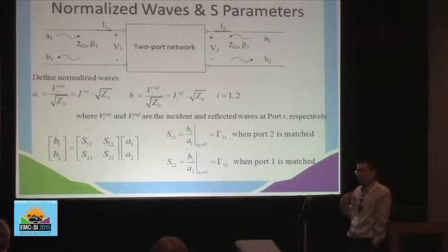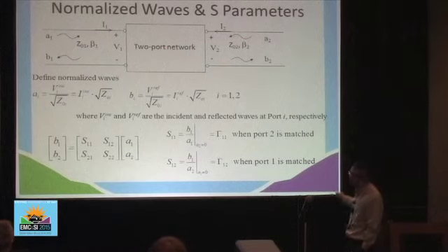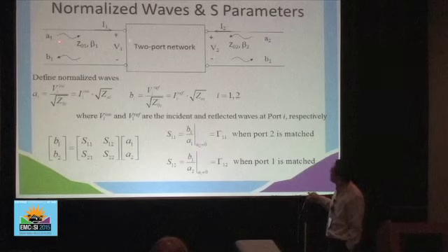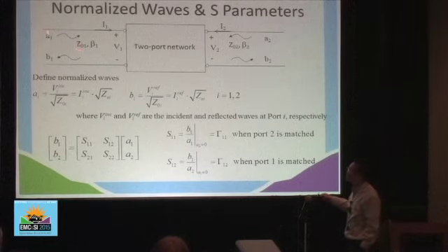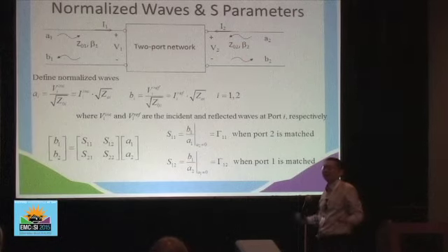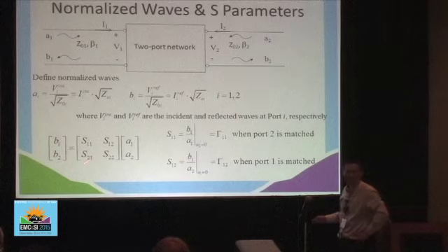So at the higher frequencies, we can assume that a network, an unknown network, is connected to two transmission lines. And these transmission lines has the characteristic impedance of Z01 and Z02. Then in this transmission line, we have left-going waves, right-going waves here. Because we have multiple ports, we don't know which is left and right in general cases. So we rather call them incident wave, the wave into the port, and the wave come back, reflected waves. So in each of these transmission lines, there's incident wave, reflected waves. Then I can relate all the reflected waves with the incident waves using a matrix. This matrix is called the scattering matrix, S parameters.